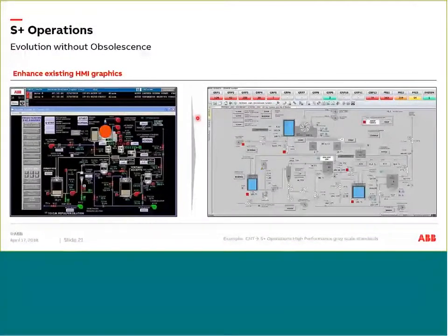The other thing that we also provide is enhancing the graphics. As opposed to just preserving the graphics, we can go in and convert them to the high performance philosophy that's out there. So we can take the graphics and update them, as opposed to only converting them. What we have done with a couple of our users, and this is an example of PC View, is translate the graphics as is, and then slowly, as time progresses, go through different parts or aspects of the plant and enhance those graphics from PC View to the latest high performance or even color-coded schemes, depending on what's relevant.